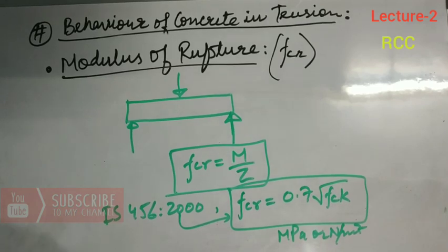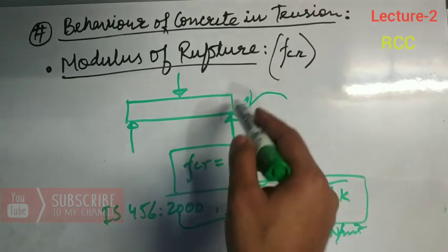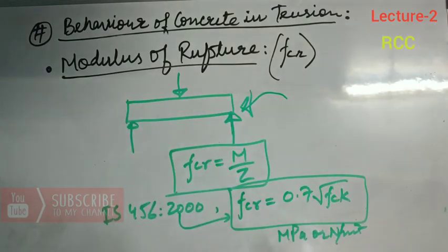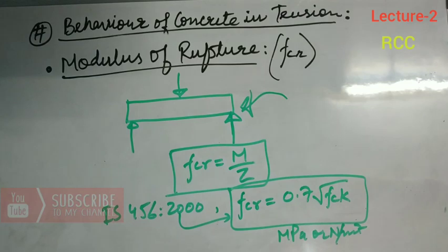By explaining modulus of rupture, I have also explained you the flexure test that is performed on PCC beam. It may be rectangular and subjected to a single point load or 2-point loads. Now, second one is split tensile strength of concrete. So what is split tensile strength?